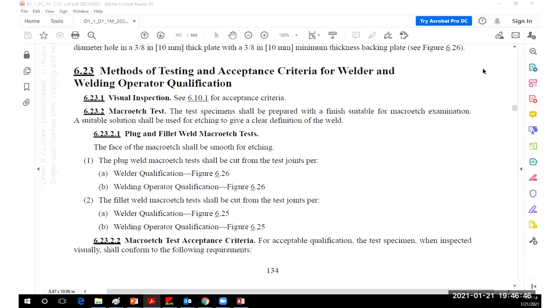Well, you've done the welder qualification test, and it doesn't get any easier than meeting the visual acceptance criteria of Section 9. If you were to just go by it by itself, it's almost embarrassingly easy. I think they're talking about changing it, but I don't think they have yet. Essentially it has to have full penetration, be fused, and can't have any cracks. It has to be filled to the joint. There's no acceptance criteria for undercut in ASME Section 9. There's no acceptance criteria for reinforcement, for overlap, for any of those things, for performance qualification.